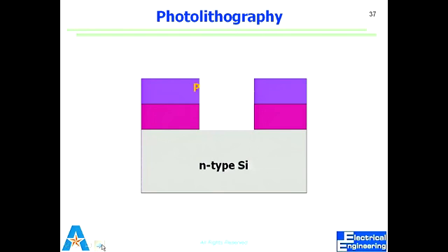What's a very common material we use to remove dried-off chemicals? So we have chemicals that dry off. Acids? Water? Acetone, right? Nail polish remover. So chemicals like acetone can remove photoresist. And I don't need the resist because I've transferred that pattern into a hard material, which is silicon dioxide.